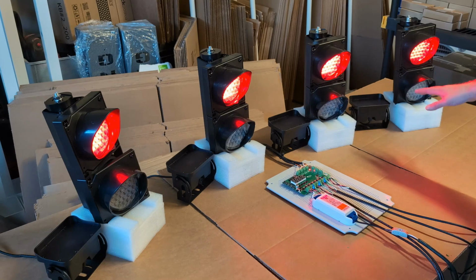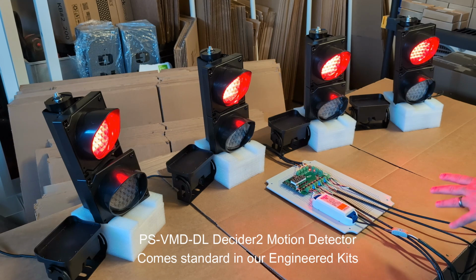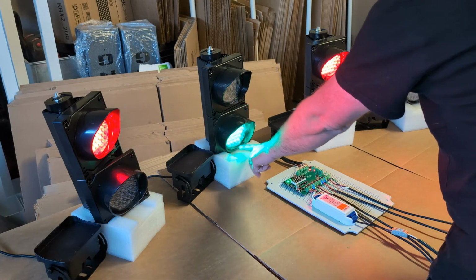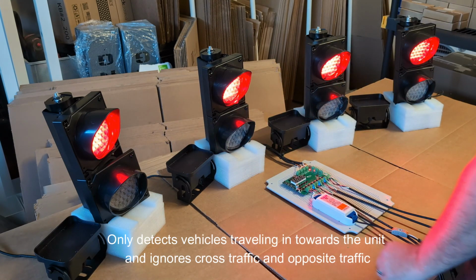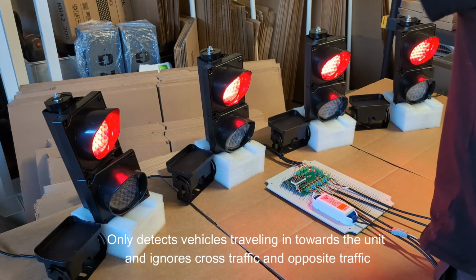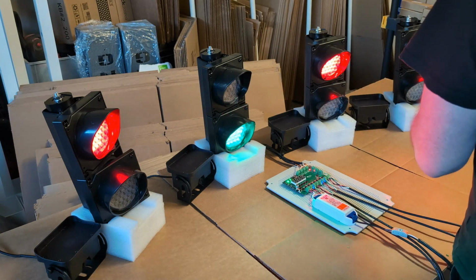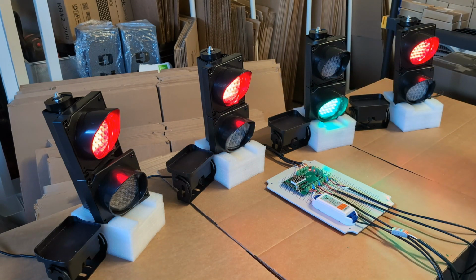Here I'm using a vehicle motion detector that only detects vehicles approaching the detector, not vehicles moving away. This prevents false detections in cross-traffic intersections. Let me demonstrate. As I approach it, it detects it. If I come up to the motion and reverse, it does not detect it, but as soon as I go back towards it, it detects it. This minimizes those false alarms on cross-traffic intersections.